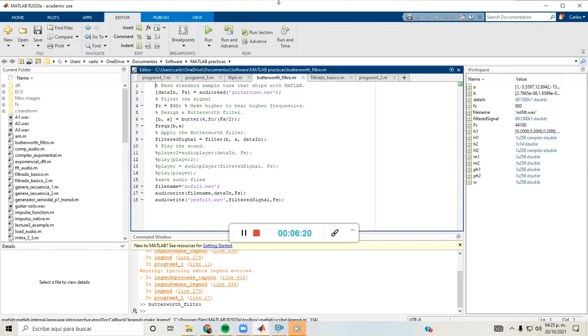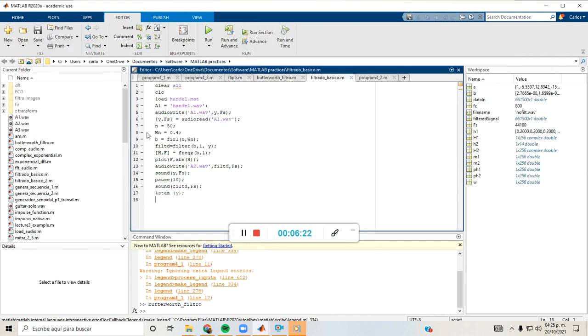Okay, and we are going to take a look at one last example using a finite impulse response filter, which is going to be declared here using this Matlab function, where we need to declare the cutoff frequency in radians per sample and the filter order here. Remember, the bigger the order, the better the filter. In the analog domain, this can be quite tricky, but in the digital domain, we just change the numbers here.